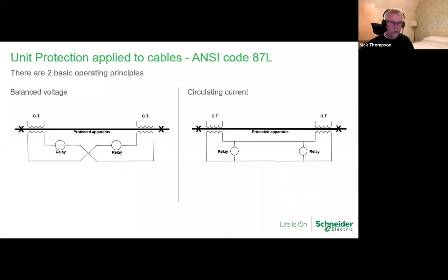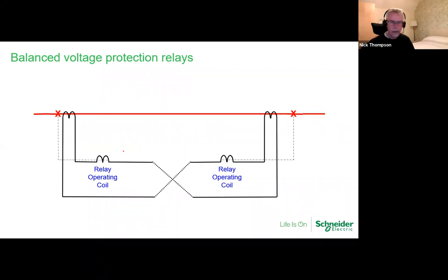There is a crossover on the cable, and I'll talk you through how it all works here. So that's the crossover that you want to watch. So you've got CTs at both ends. We have our protection relay, and ultimately the protection relay will trip both circuit breakers. So let's walk through how it all works. So we have our simple scheme here: circuit breakers at both ends, CTs on the cable feeders on both ends, relays, etc. And this is the crossover.